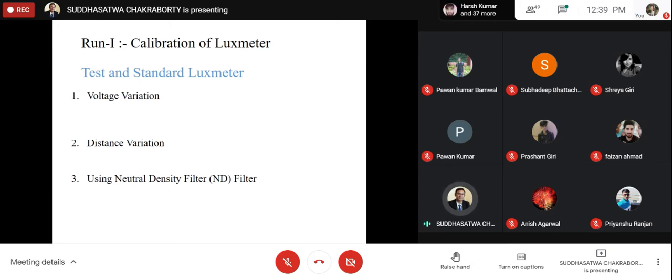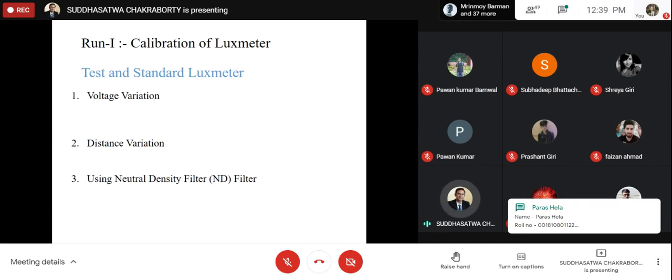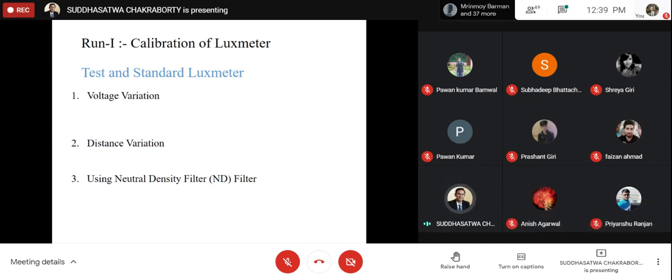Calibration is very much used in any measuring instrument. In your second year, you have performed the calibration of ammeter, voltmeter, and the wattmeter. You have calibrated, right? In our electrical lab. Calibration is basically knowing the measurement with respect to a standard value. Right. So it is represented at percentage sort of error. So the outcome of the calibration should be a percentage error, but it's not an unique value of percentage error, because at each range of reading where you are measuring range of the equipment, your percentage error may vary.